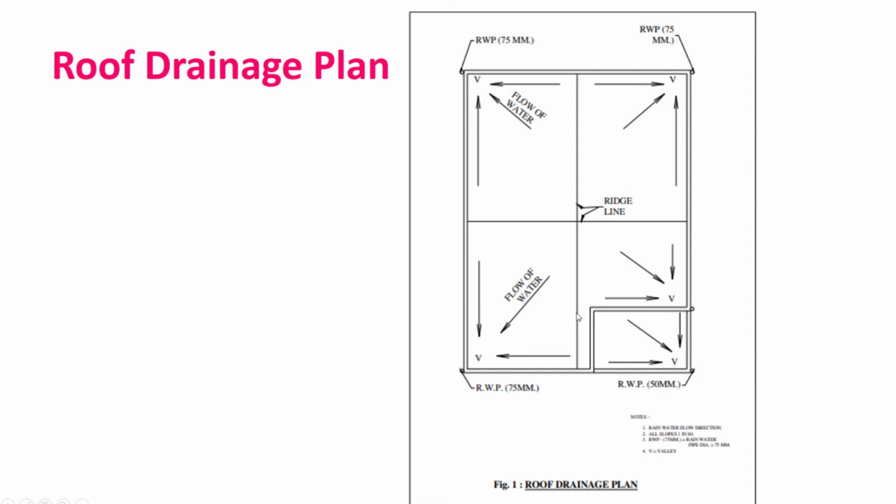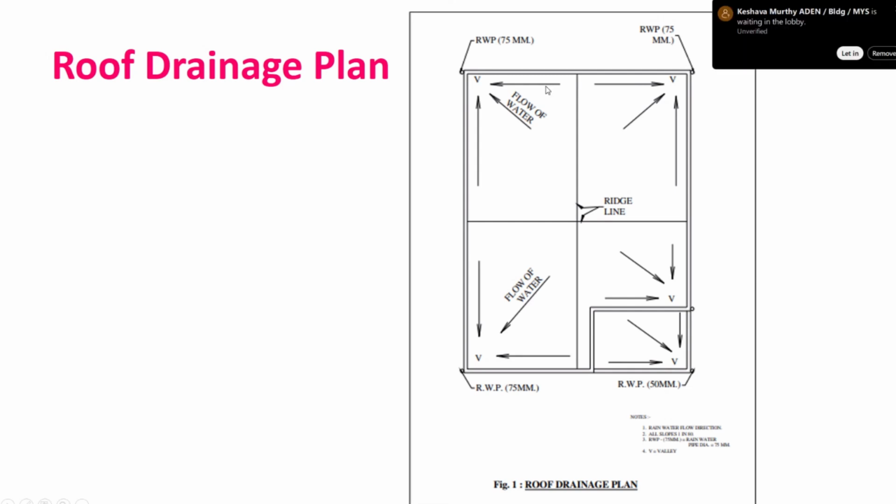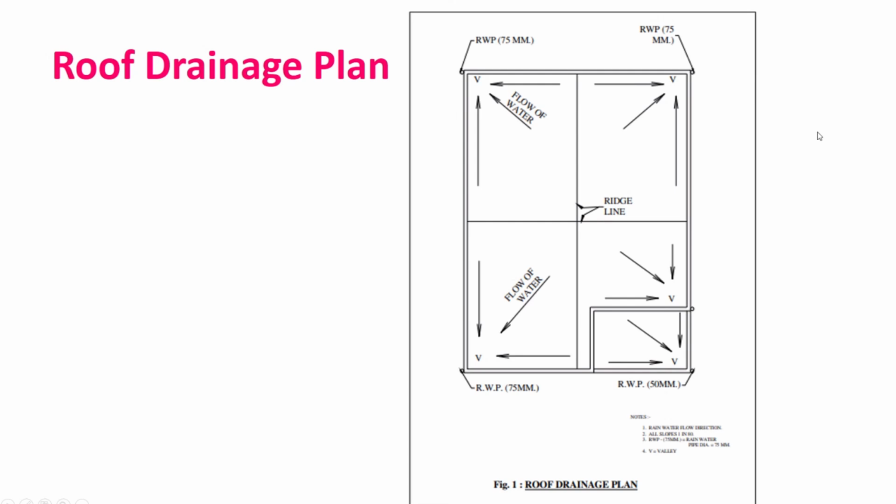And the second important thing it says is that in case you have provided any type of name board of that particular society or of that particular building, or any structure over the main entrance at the boundary wall, the minimum clearance shall be 4.5 meters. You can understand it should be 6 meters wide, the gate, and in case you have provided any type of covering over that gate, it should not be less than 4.5 meters so that the fire tender can enter into the plot.